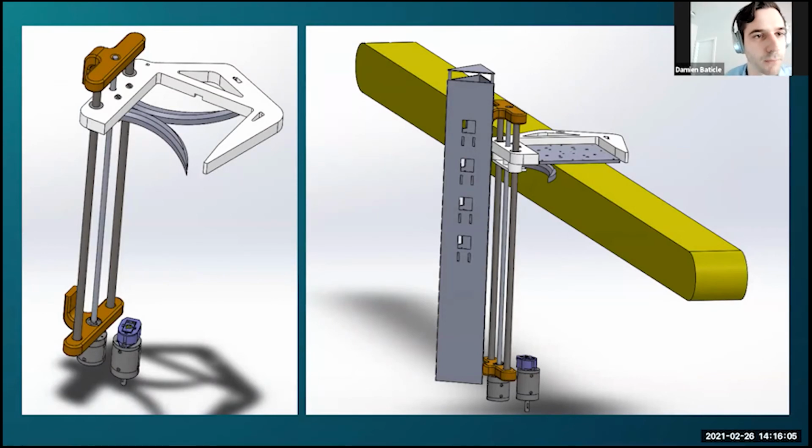solution. On the left side, you see the gripper with all the parts, and on the right side, you see how it would go next to the conveyor, the arms spread apart. It would grab the work tray back up, and because on the arms there are torsional springs, the arms would come back out and immediately support the work object.